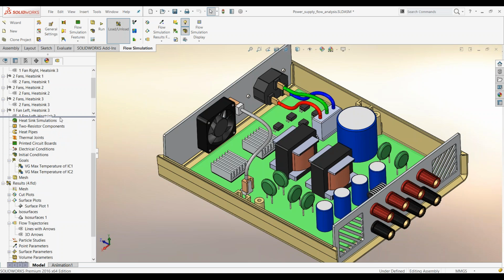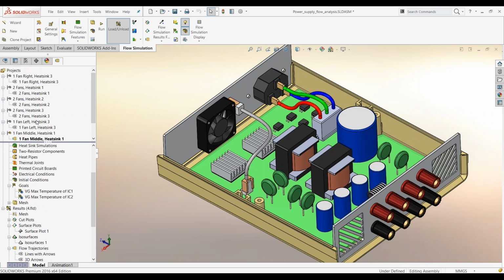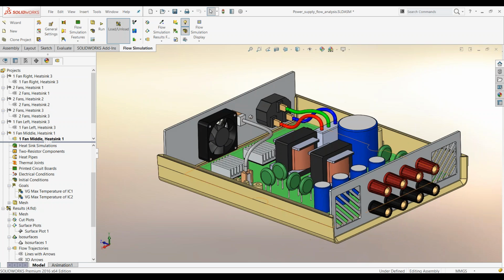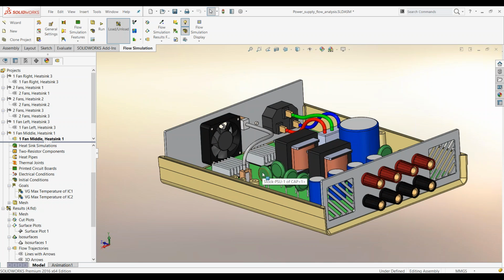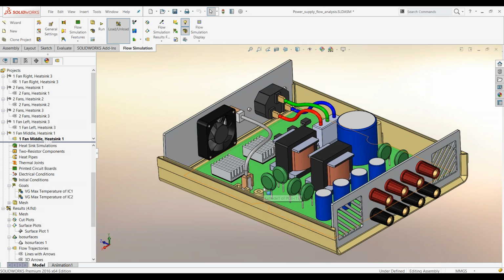Design criteria will come into consideration in deciding whether to use one fan or two fans in the system. Of course, if you use one fan, it will be slightly lower cost, and at the same time you also achieve lower noise in the system. If you're using two fans, you will have a lot more noise compared to this system. So we go through the variables of having one fan, two fans, and different heat sink designs in the systems to achieve the objective of 100 degrees C.